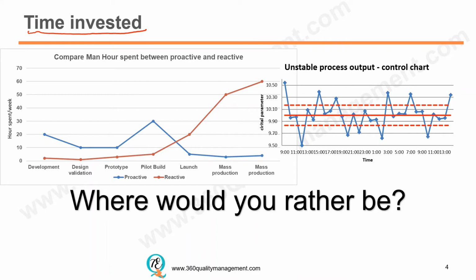Proactive means that time spent upfront in the early stage of a product life cycle, such as development, design validation, prototype, and even pilot build, to plan in quality and analyze the potential risks of the product, followed by monitoring closely the performance of the key metrics in each stage, and fine-tune the process before mass production.